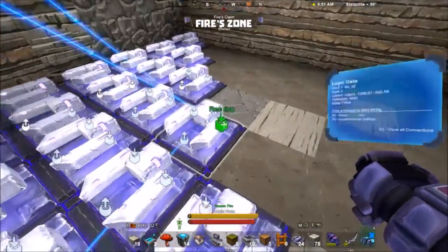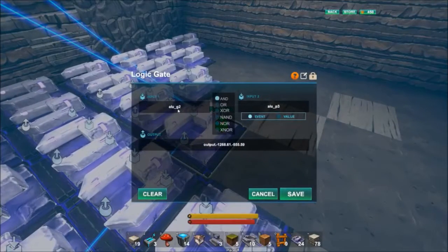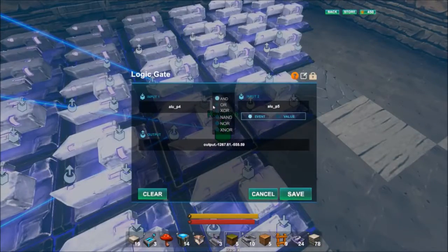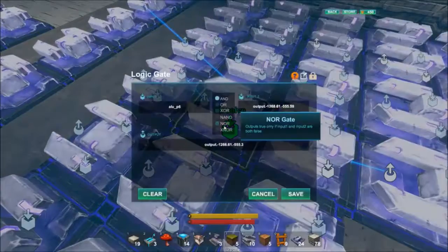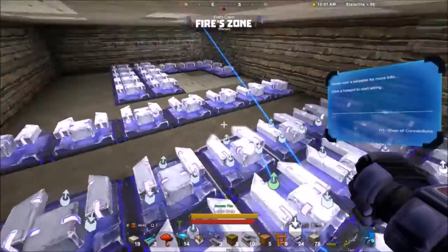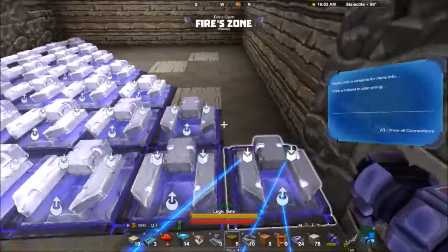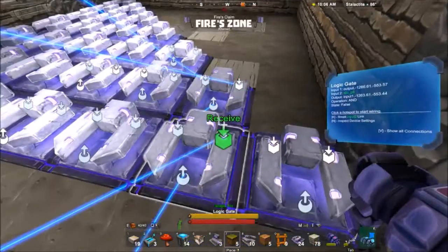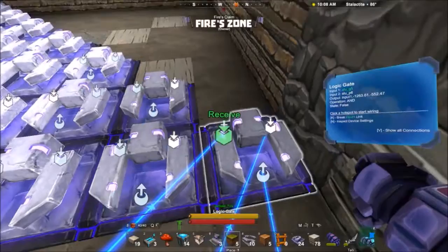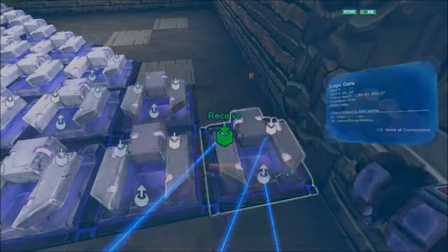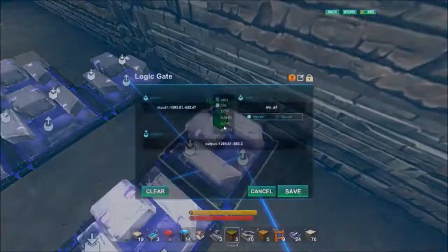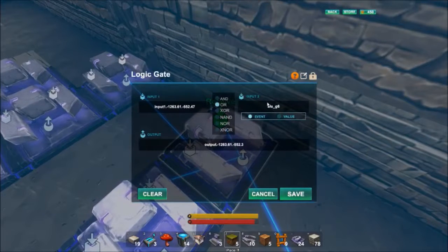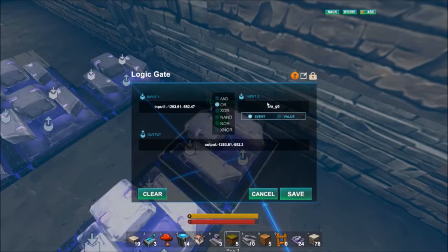Then this one will be when it's generated at G2 and bit 3 propagates it, bit 4 propagates it, bit 5 propagates it, all the way to bit 6 propagates it. Then it will reach bit 7. So they all have to be propagated by bit 6. So this is generated by 4, propagated by 5, propagated by 6. This is generated by 5, propagated by 6. And the last one is just when it's generated by 6. That doesn't have to be propagated by any, because it's generated on the bit before bit 7.